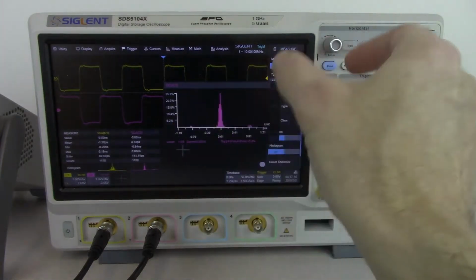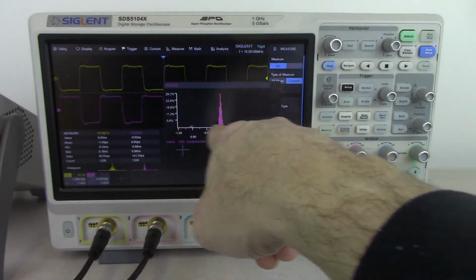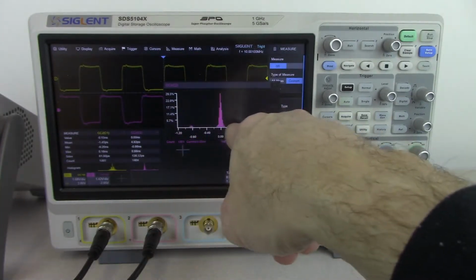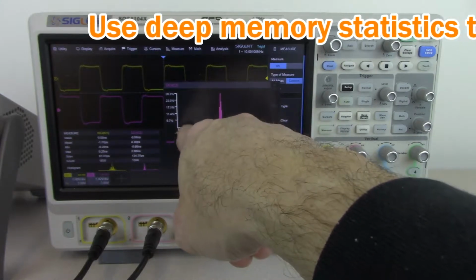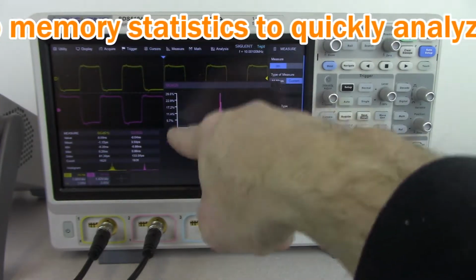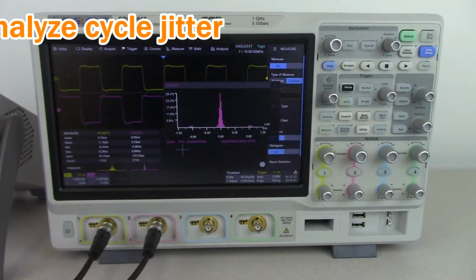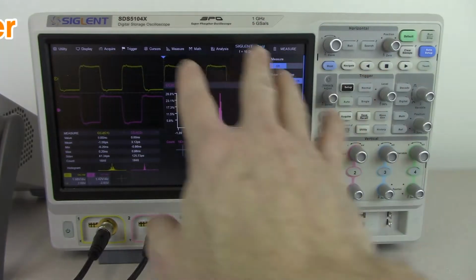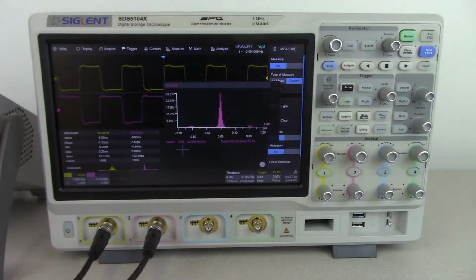Basically, the jitter is quantized, and that's very easy to see as we start to collect those statistics. Every once in a while, we're getting a bin over here with the jitter or the rise time, and then we get the rise time here. So the cycle time jitter is actually fluctuating between these two. It's a very, very easy way to take a quick look. We'll let the clock run for a period of time, and then we can see whether the clock has some kind of deterministic or quantized jitter.